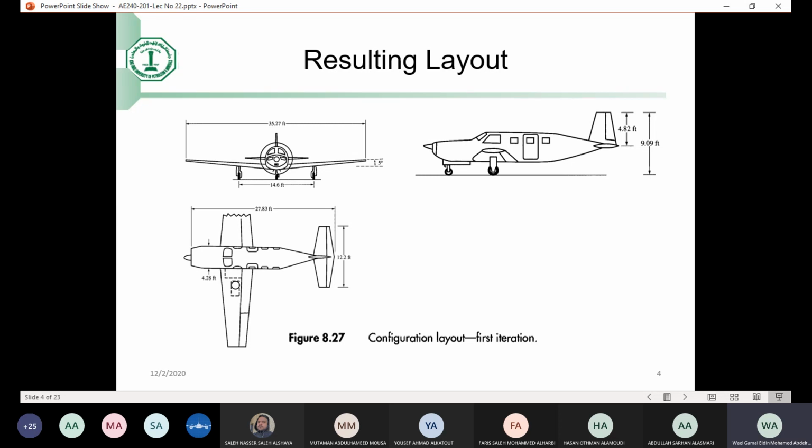Now, people have done so in so many ways. Earlier, what they did is make a model made of wood, for example, and they would cover that fuselage, sometimes with graph paper, and they simply counted the number of squares. That will tell them the external surface area. Very rough, but very simple way to get it. Others would coat the model, maybe with cadmium or nickel, just like you coat jewelry, and they calculate the amount of coating, and that will tell them the external surface area.